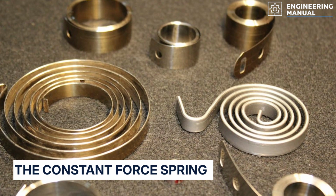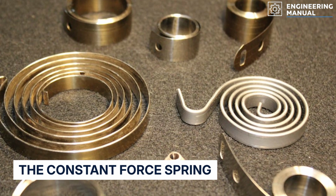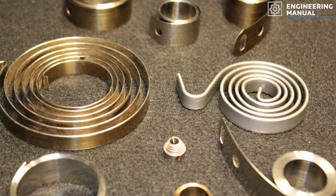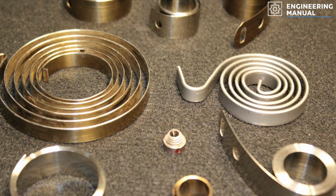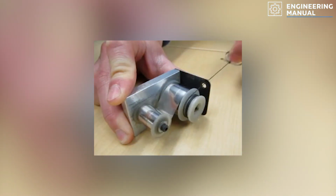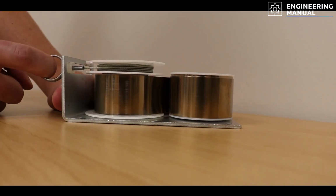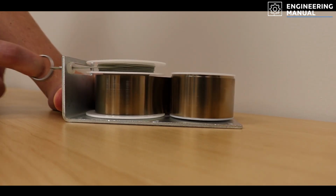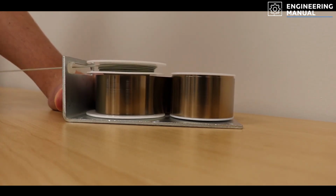The constant force spring is a flat strip of pre-stressed steel wound into a coil that exerts nearly uniform force across its extension range. Behavior comes from elastic bending of a pre-curved strip, which attempts to return to its original radius of curvature. Unlike coil springs, force does not scale linearly with displacement. It remains approximately constant until near full extension.